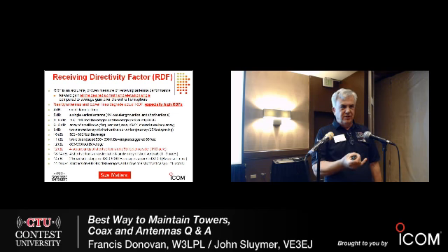But it has to be local, it can't be skywave propagated, and it has to be vertically polarized, which it turns out most local noises are. But if there's some odd case where that local noise is horizontally polarized for whatever reason, the vertically polarized loop is not going to null it out.